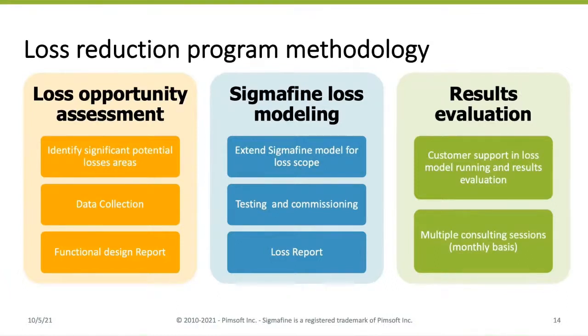The Sigmafine model will need to be adapted in order to support the loss accounting step, and the production also of a related report like the ones we have seen before. After running the balance for a few months, the results need to be assessed compared with the initial baseline, and again, actions taken based on the new results. After 1 year, a new baseline can be created, and this can be compared to the original. And from the comparison between the older and the new baseline, the overall benefit can be calculated.